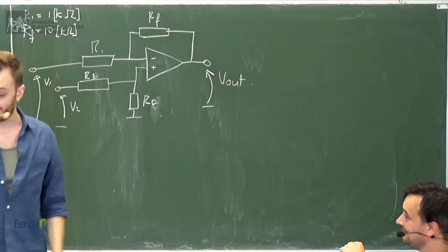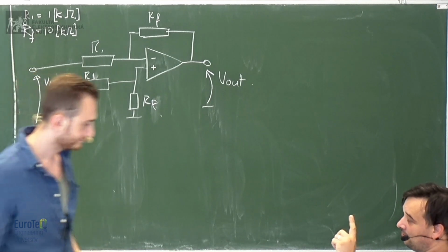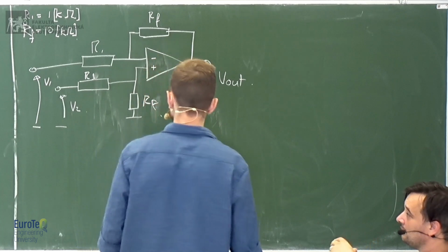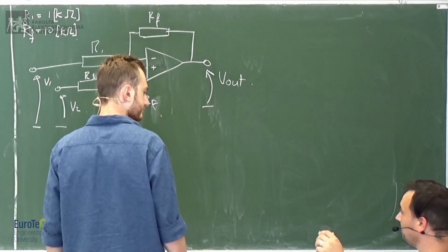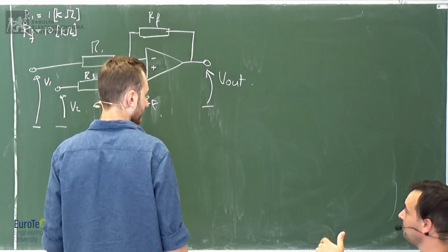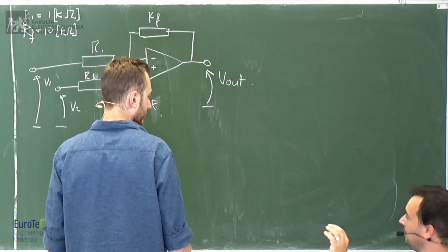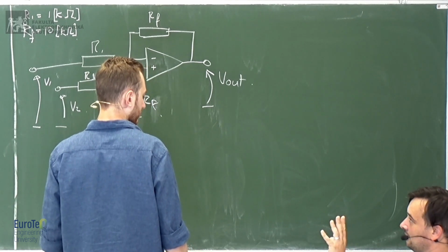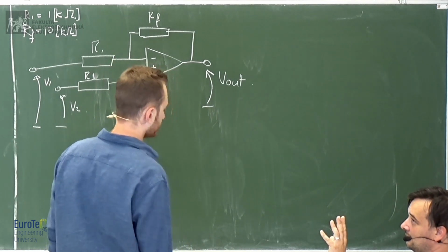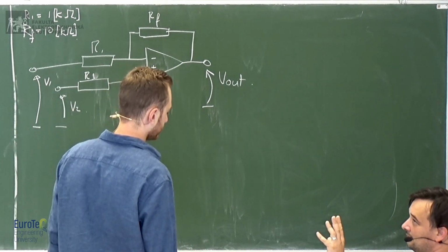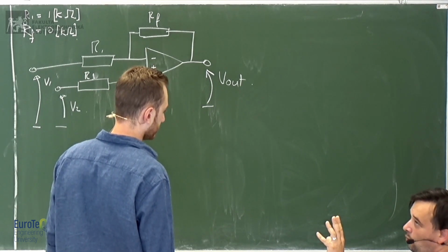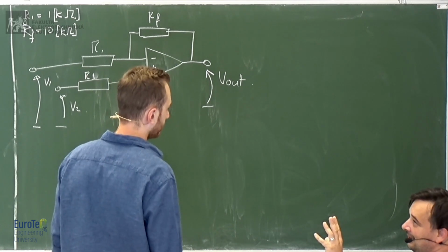Difficult? Actually, it's not, as long as you use the, how do you say it in English? The principle of superposition. Superposition, okay. When can you use the superposition effect and what is it? Well, it is when you have multiple sources in a circuit and you can replace a voltage source with an open line and a current source with a closed line. Opposite, excuse me.